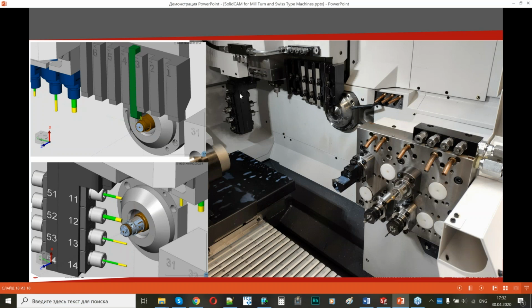And also what I want to mention here is we don't have turn drill tools here. We have two turn drilling operations for the GenFA machine, but here we don't have this attachment. We have only OD turning, radial milling, and B-axis milling tools. But we have some tools for deep drilling on the back spindle, and I'm going to change the type of operation so this drilling will be performed with the tools on the back spindle. So I'll try to do this quickly.